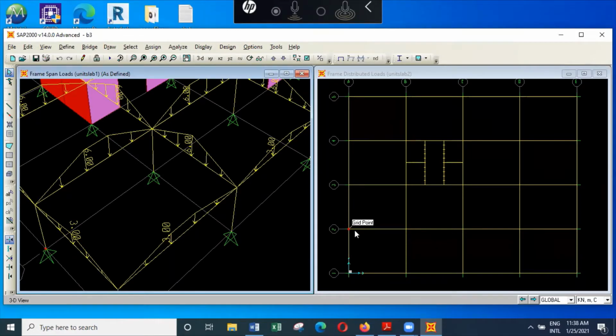And when you have trapezoidal load distribution on this beam, you'll have a triangular load distribution onto this beam, and a triangular distribution onto this beam, but the load will come from both sides. You get 3 meters here, 3 meters here, so altogether 6.